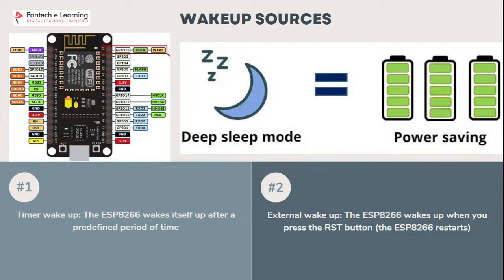This is the most power efficient option. The ESP chip only draws approximately 20 microamperes. However, if you use a full featured development board with a built-in programmer, LEDs and so on, you won't be able to achieve such a low power state.